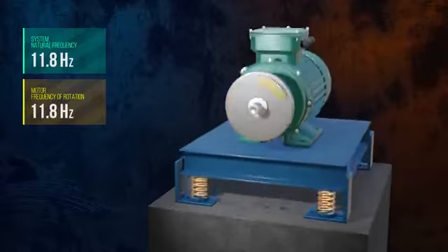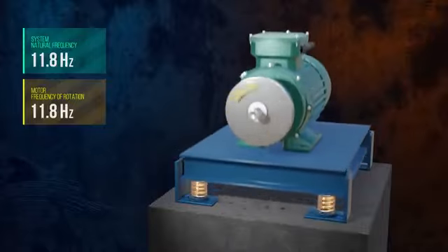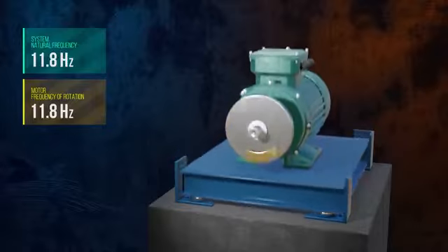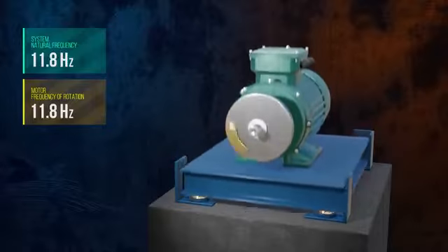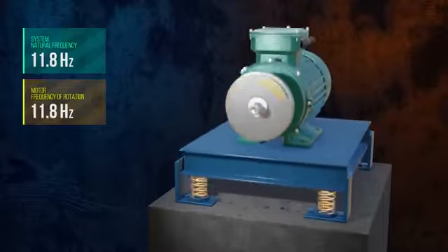This happens because when the natural frequency and forcing frequency are the same, the energy added to the system by the external force is timed just right so that it increases the amplitude of the displacement with each cycle. This is called resonance. Resonance can be very dangerous and needs to be assessed carefully.